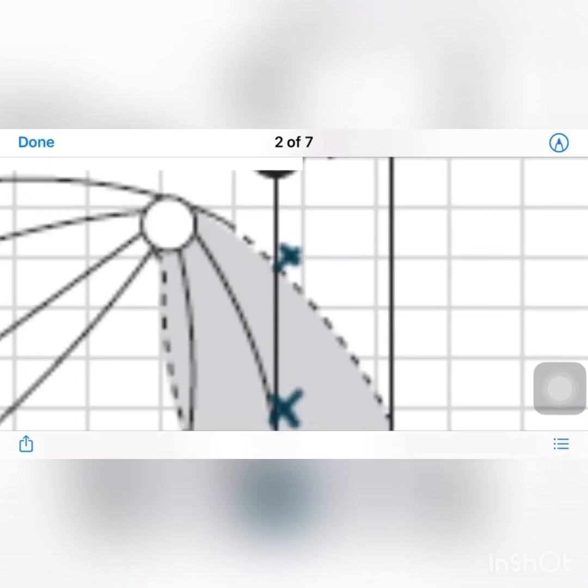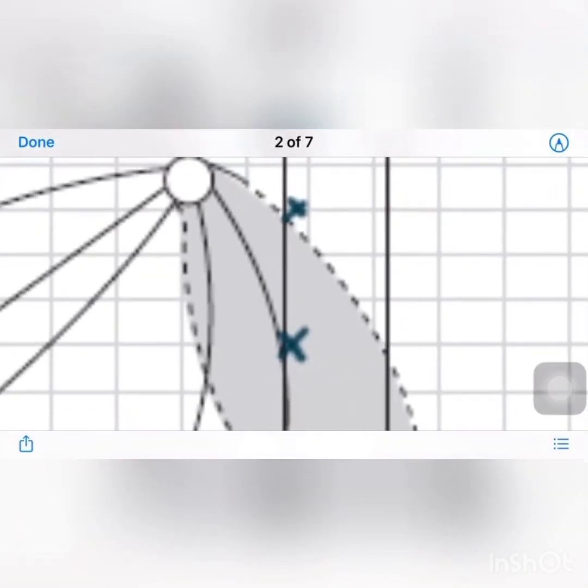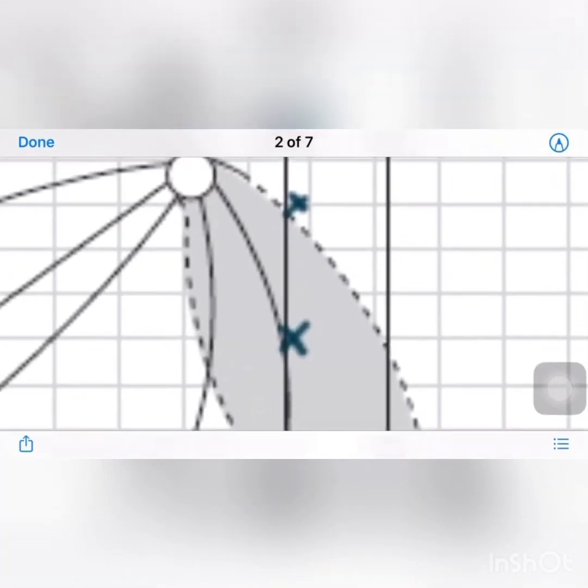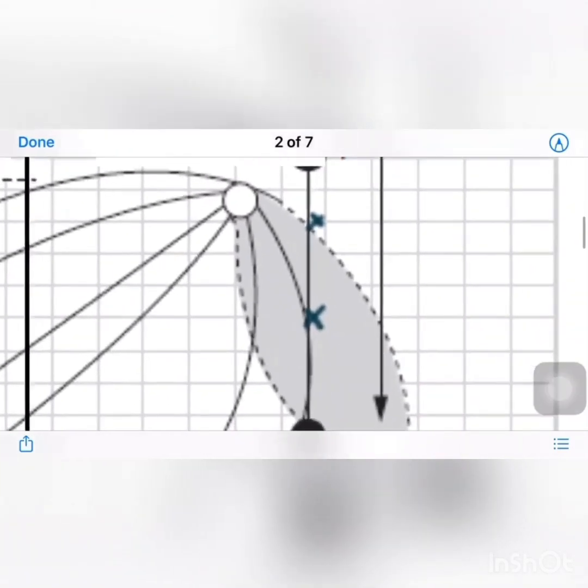If we decrease pressure, we have an increase of liquid phase. It's a reverse condensation, one of the famous phenomena in thermodynamics. We call it retrograde condensation. By decreasing pressure, we have an increase in liquid ratio in our system.